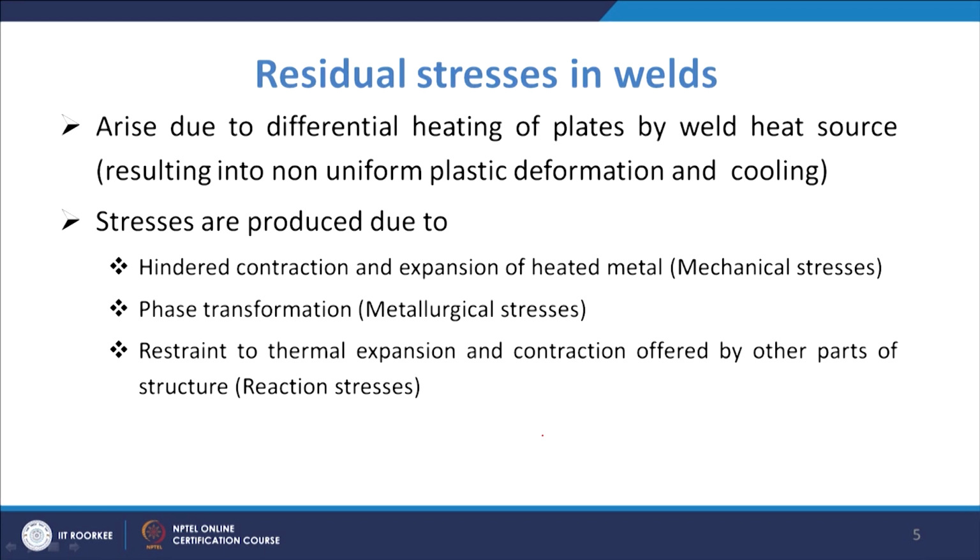When you have hindrance to the contraction and expansion of the heated metal, because many a time you have equipment or phases with different expansion as well as contraction. Because of their hindering nature, as they are attached to each other, you will have stress development inside, and that is known as the mechanical stresses.